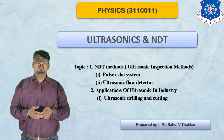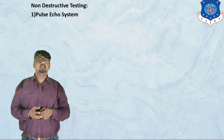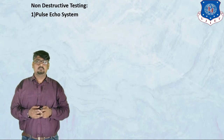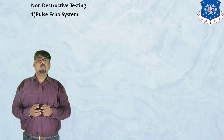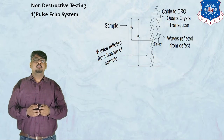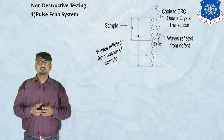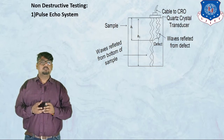So, let us start with the first topic of today's session, that is the pulse echo system. The pulse echo system is the most widely used ultrasonic testing method. It uses a single transducer for both sending and receiving the ultrasonic waves.